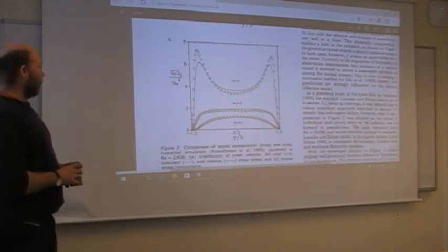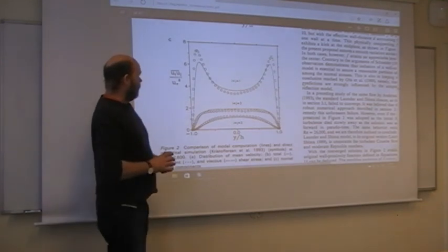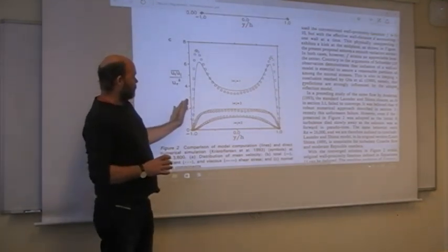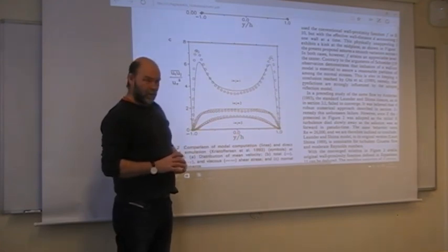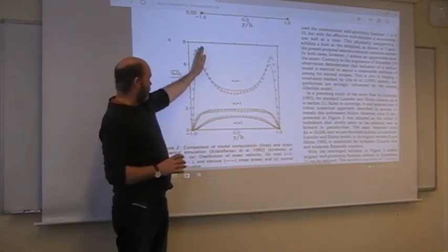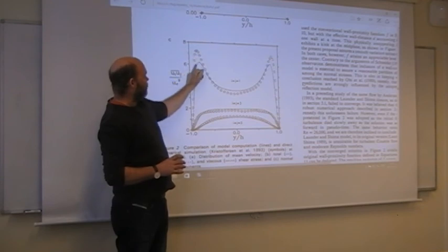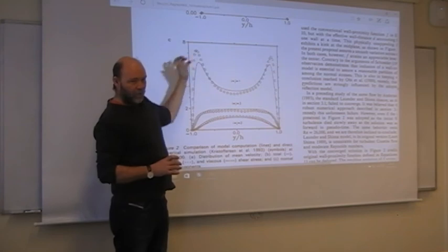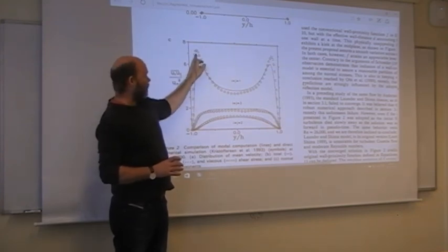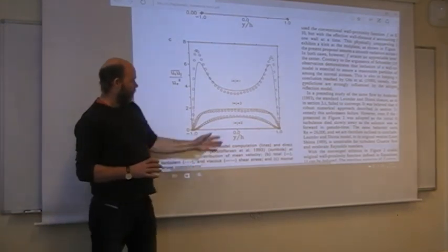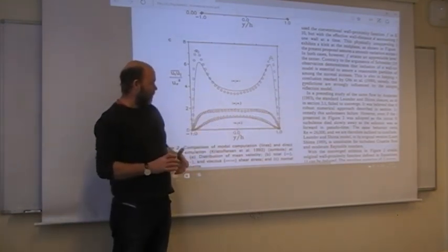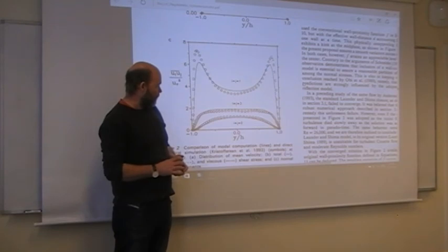The different intensities. And here in the streamwise direction, that's where most of the action takes place. And again, also here, very close to the walls, they peak very close to the wall. So here you have a lot of the turbulent activity. Here is where the production of the turbulence takes place. For the two other components, in the spanwise and the cross-stream direction, much lower.